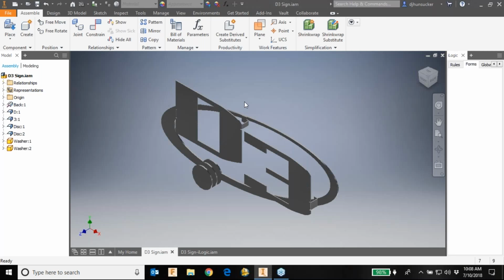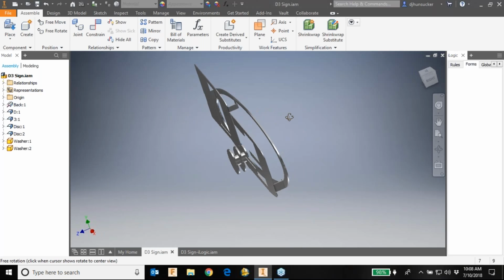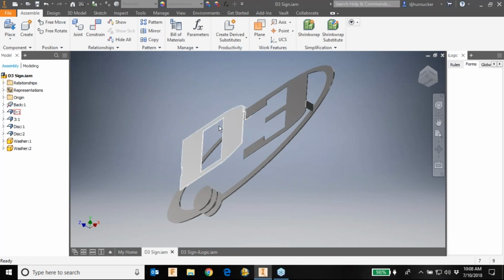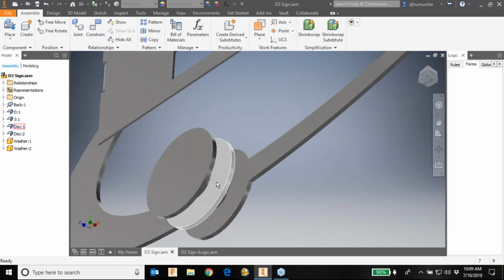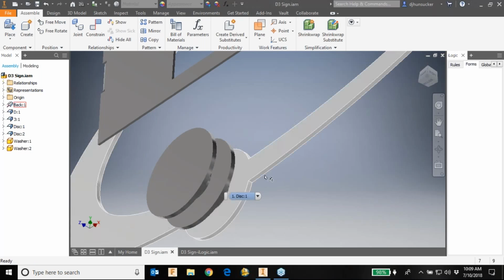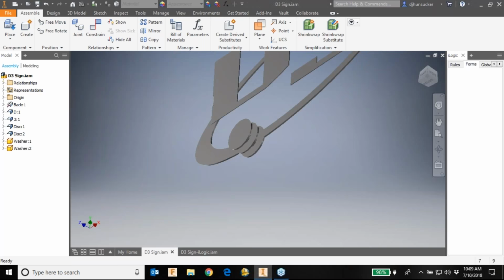So if you have the collection, you have nesting available to you. Nesting is a great utility for sheet metal assemblies or sheet metal parts. And the key thing there is it has to be a sheet metal part. It has to have a flat pattern for nesting to work. So I've built this simple assembly with 3 parts here, and there's a couple of flat plates in here. Even if they're flat plates, they still have to have flat patterns in there.